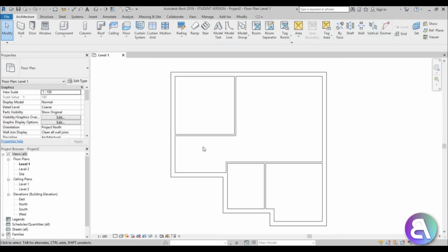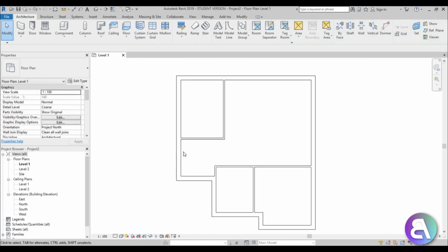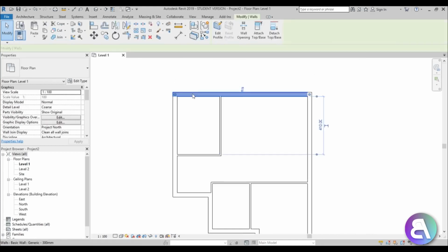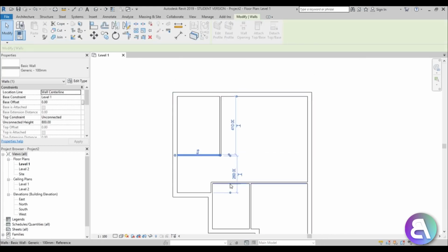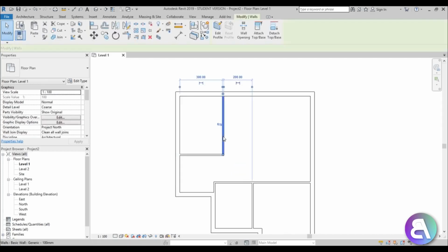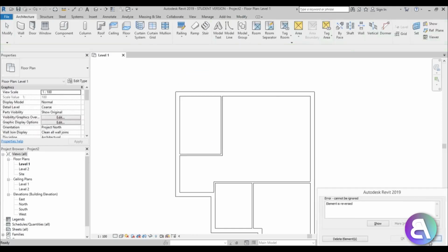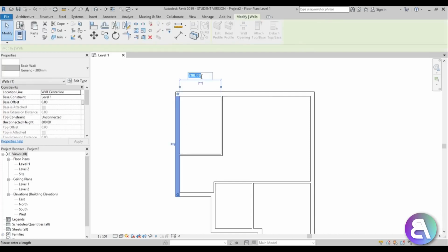Okay, so the next thing, let's go over here. For this entranceway we only need it to be kind of like that, and for this walkway let's make it a generous walkway. Let's leave it at 184. And for this, let's just kind of leave it there, but let's make it a bit wider. Let's do at least like 4 meters, or let's do 3.5. Oops, that's 350 centimeters, sorry.